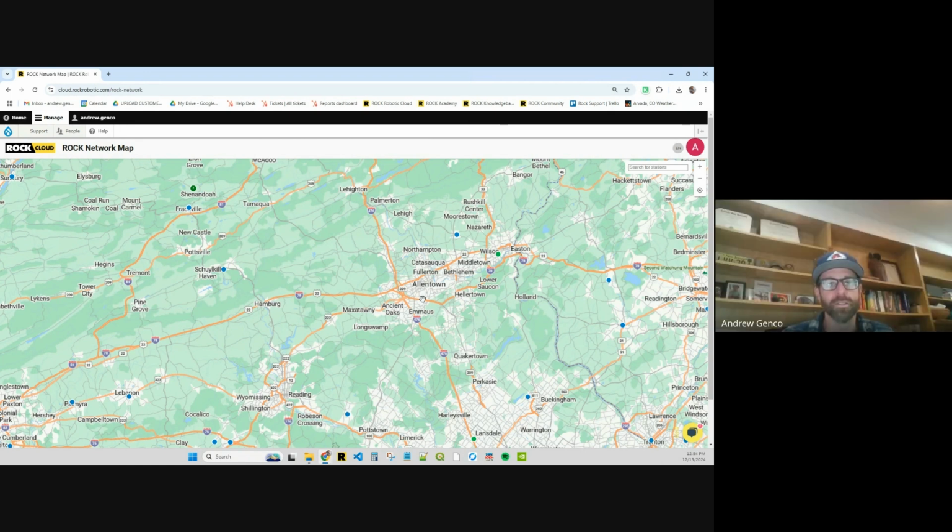I mean, you can always think of the CORS network and the CORS stations as that backup, but I hate to use the cliche, but you get what you pay for, and since you don't pay anything for CORS, there's no guarantee it's collecting from all the constellations. There's no guarantee that it wasn't down, things like that.